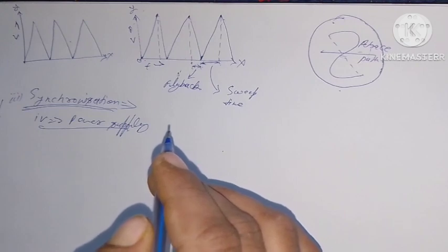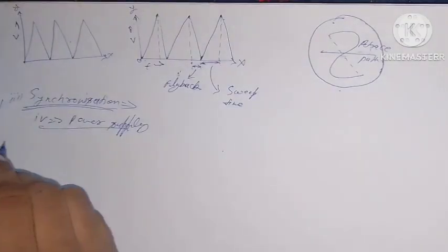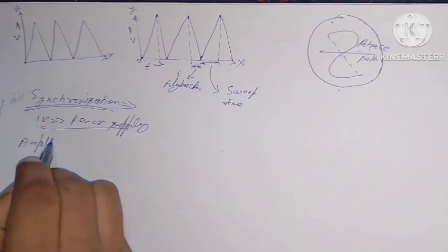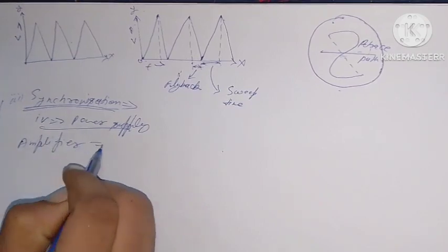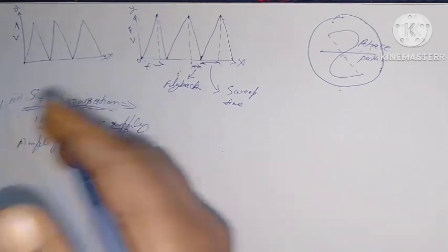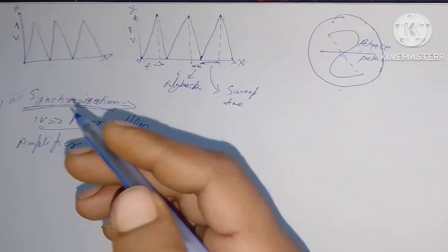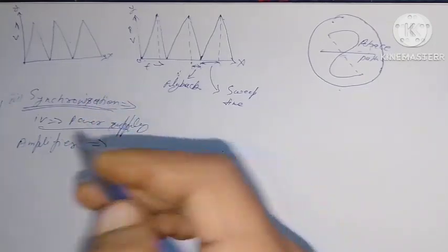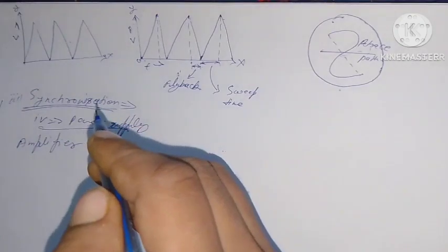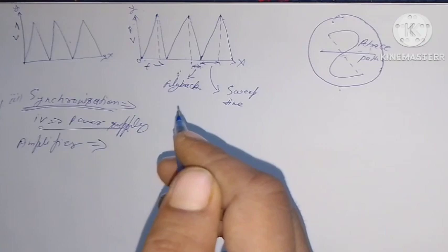Okay, and next is amplifier. To amplify the weak signal so as to increase the deflection in the vertical and horizontal direction without distortion of the incoming signal, the X and Y plates producing the vertical and horizontal deflection are connected to suitable amplifiers.